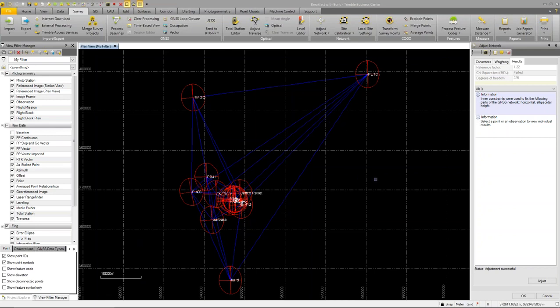So because all these vectors come from GNSS processing, they all are a common data type. Their error source comes from the common observation of satellites. All 3 components of those vectors, the azimuth, the delta height, and the distance, all have errors that derive from the processing of the raw GPS data or GNSS data.